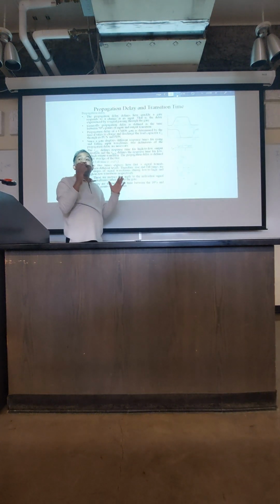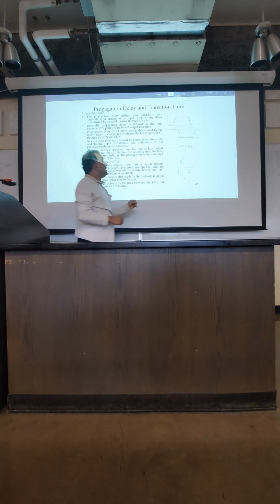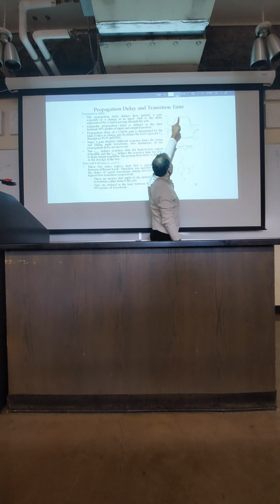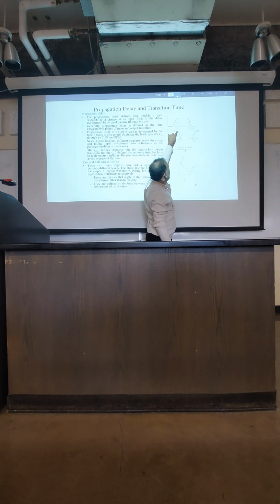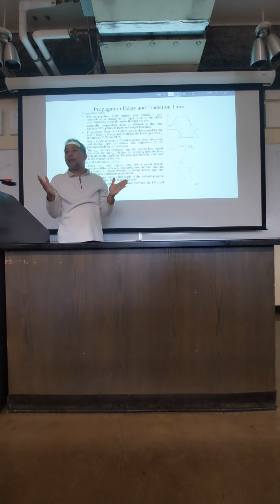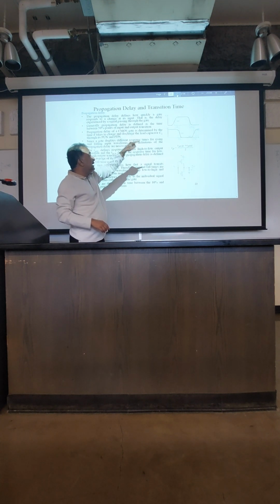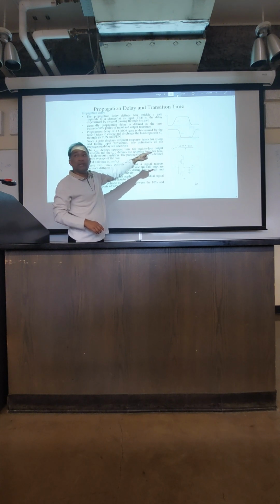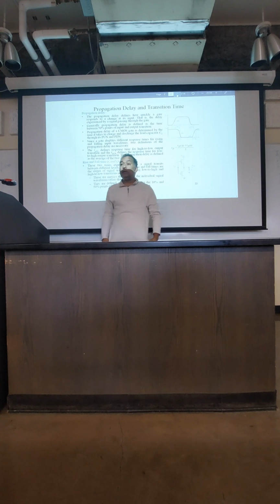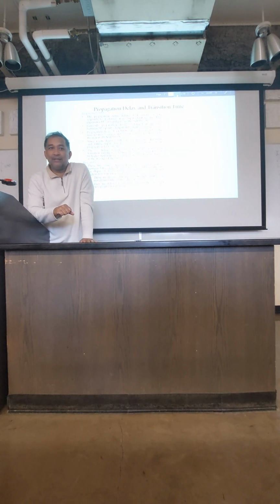If both signals are ideal and symmetrical, it will not be a matter. We can take the initial point of the input when it starts going up and the initial point of the output when it starts going down. The time difference is our propagation delay. Or the final destination of the input VDD and the final destination of the output 0. If we take those two timestamps, that difference should be our propagation delay, right?